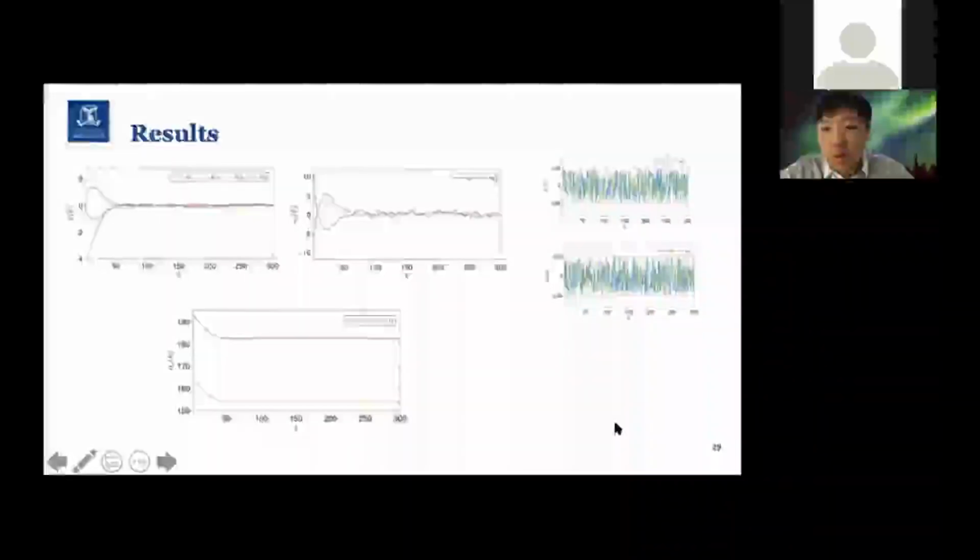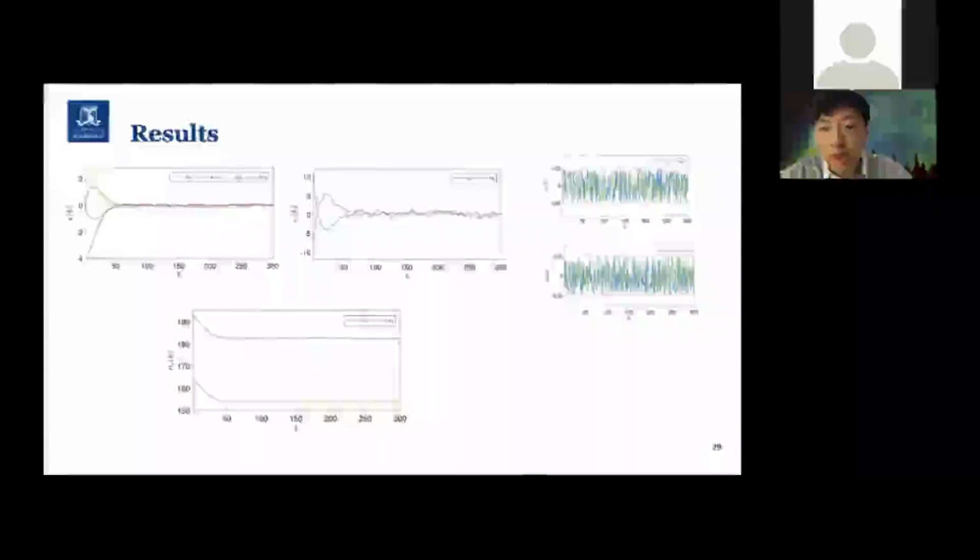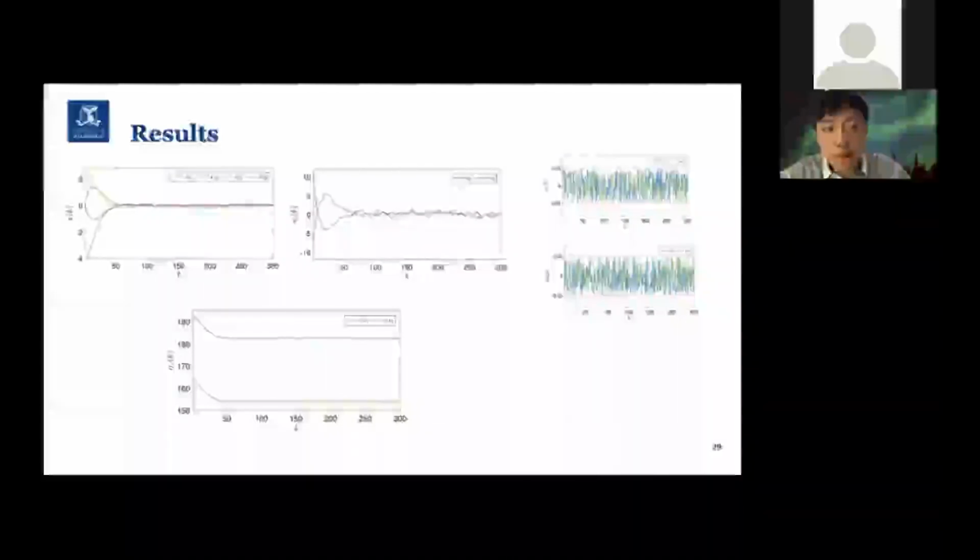So in the simulation, we also transform the conditions for the robust adaptive local terminal sets into LMI conditions, and we also plug in the constraint. This set should be inside the constraint for the state and input, and then we also convert it to LMI conditions. And then we run this optimization problem online in real time, with some sampled disturbances with random values within the given convex sets. And this is just a simple run.